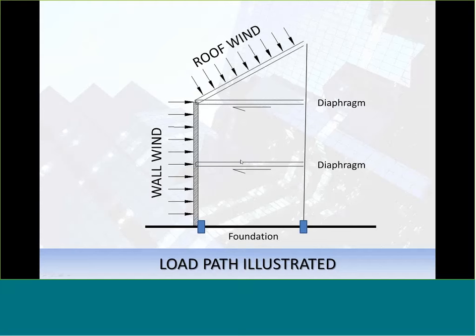Those diaphragms will distribute those loads based on a wind load or a seismic load. We apply that to the walls. It gets distributed through the diaphragm into the walls and into the roof, and then distributed through the structure all the way down into our foundation. So the diaphragm is the loading mechanism by which it distributes that load. How that load gets distributed is based on what kind of diaphragm you choose to use.